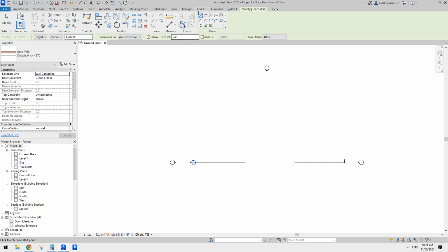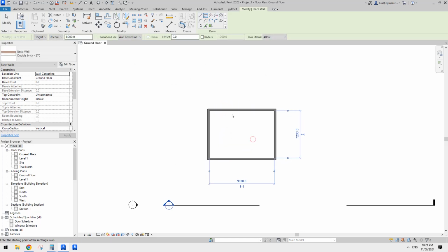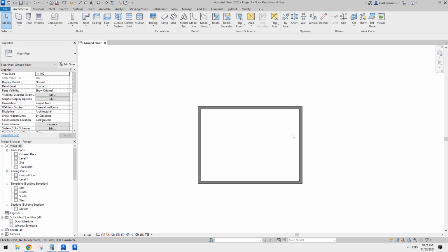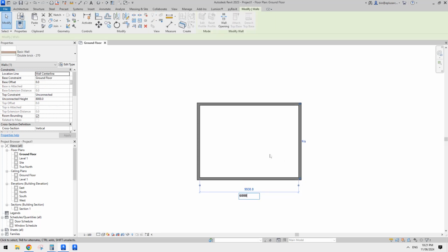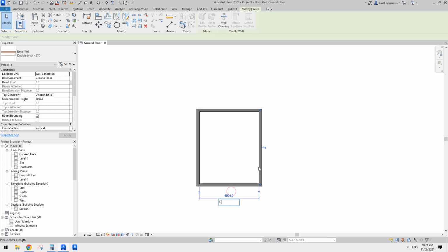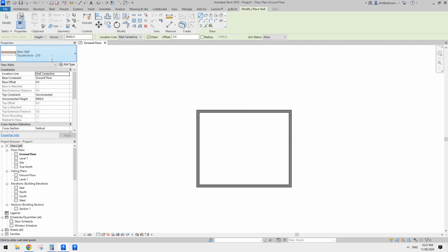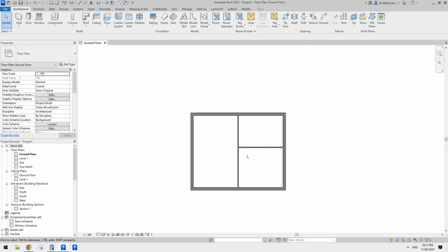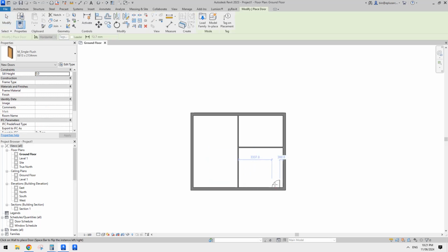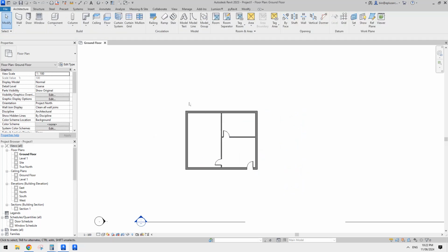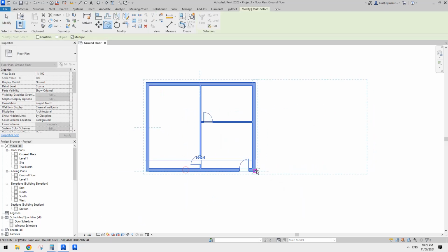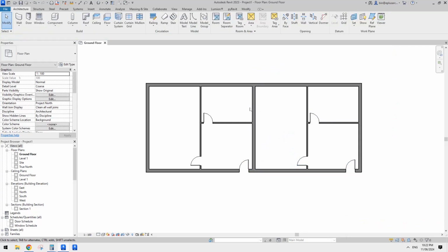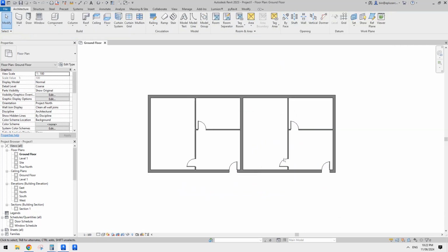So first I'll just create some walls. Okay, so I'll use WA, wall, maybe just add 6 meter, maybe just 8-9 meter. Okay, so another wall, maybe just use some generic wall. Oops. CS, create similar. Okay, so just pretend this is some apartment. Okay, so just quickly place some. Okay, so that's one. And then I'll just copy this one, maybe just to here. Maybe just delete the overlapping wall. So okay, now we have two, right?